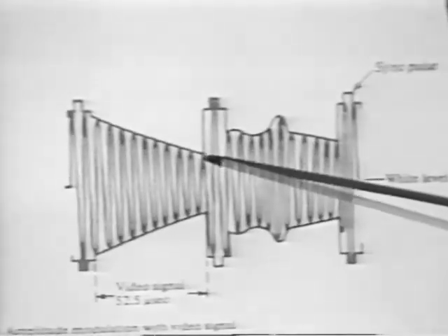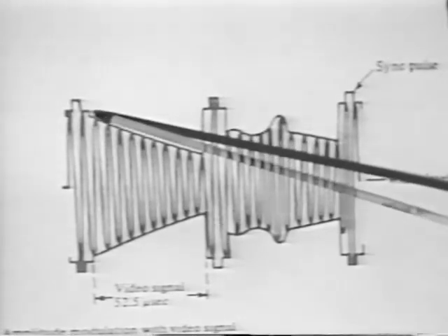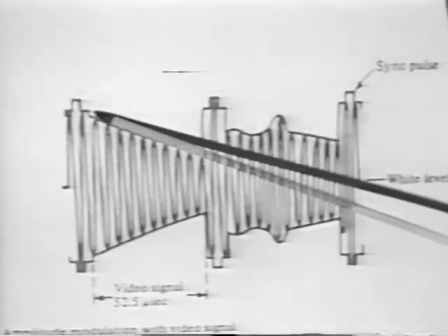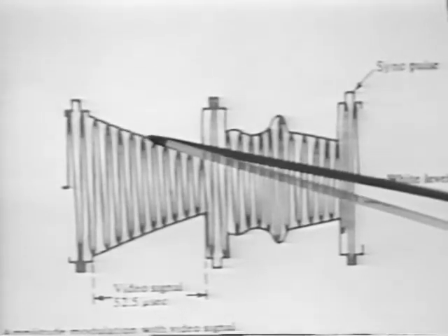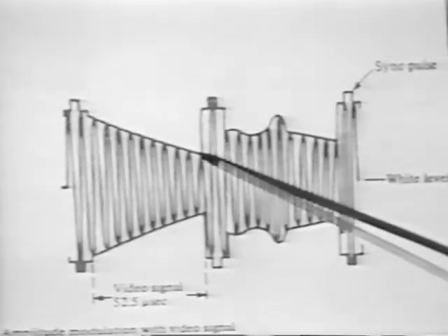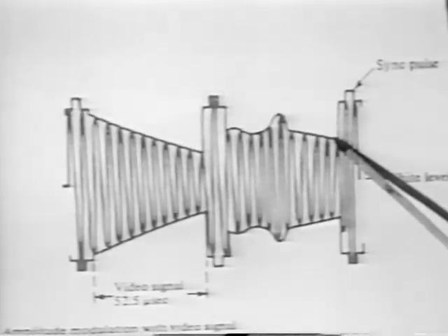This envelope here, if you recall from a previous slide, is a pattern of a few lines of video transmission. We have here the horizontal blanking pulse with a sync pulse imposed upon it, and this is used for the horizontal retrace. And then there is a scan of the line with the height of this line, the amplitude of this line corresponding to the relative brightness or darkness of the picture. So you have a sequence of pulses separated by these lines for scanning.